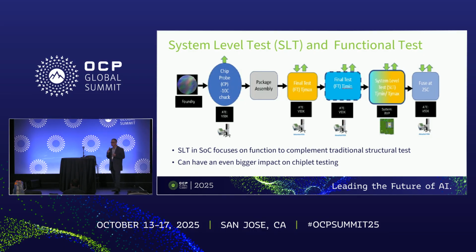Currently, all the manufacturing tests at the system level get transferred, but we are limited by the test ATE power. Automatic test equipment has some power limitation. So we have to guarantee that system level test, which is run in high volume manufacturing, is also applicable to system in a package.